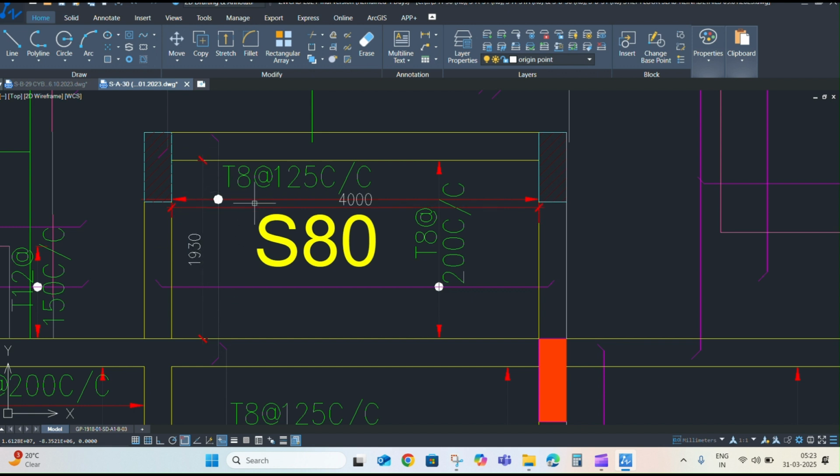Creating structural elements in AutoCAD. Drawing structural components. Beams and columns. Draw beams as polylines and columns using rectangle or polyline tools. You can use dimensions to ensure the correct size and spacing. Foundation and slabs. Use hatch patterns to indicate concrete or other materials. Draw the boundaries of foundations using lines or polylines.